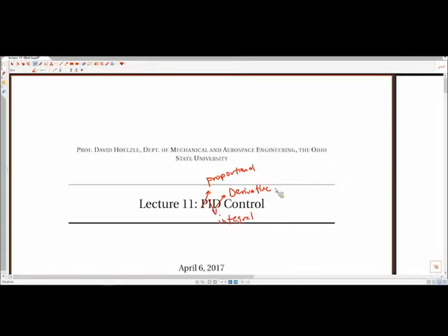We're going to go through some of the basics of PID control. I have a system up here that's going to demonstrate examples of changing PID control gains. By gains, I mean the proportional, integral, or derivative constant that adjusts how much weight we apply to each term, and show some demonstrations of the results on the system up front as well.